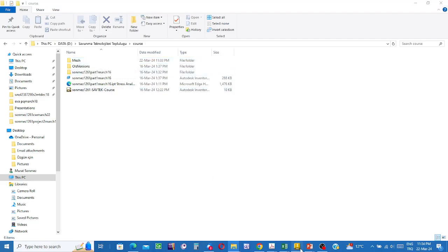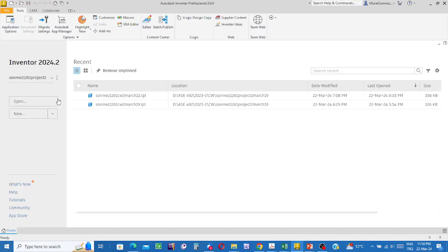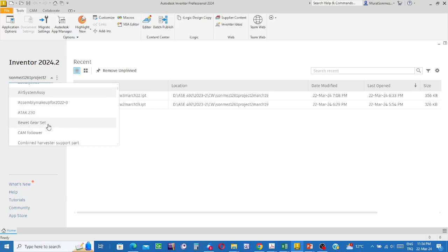And then, in Inventor, to be able to define that work as a project, the condition is that within the Inventor environment there shouldn't be an active file, and also, from the list of the names of the projects, the selected option will be not a certain specific project, but no project.